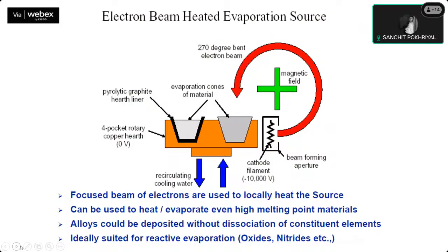Does the thin film retain the crystal structure of the target material, or does it adjust itself to the substrate? Obviously, it adjusts to the substrate. The target has nothing to do with the thin film which you get ultimately. Because it is evaporating, it takes the shape of whatever substrate you have, depending on whether your atmosphere or vacuum is there.